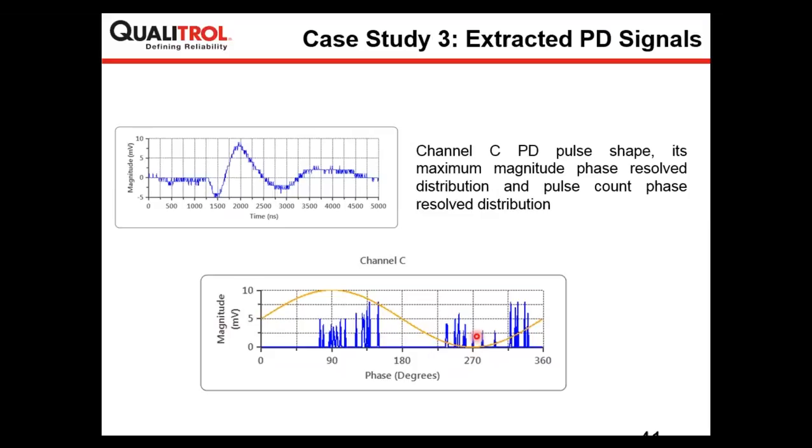So the main essence of providing all these case studies is that even in the presence of huge noise and a lot of interference, we are able to extract different activities confidently, and we can perform an artificial neural network classification, which is done automatically, and it classifies between partial discharge and the noise signal.